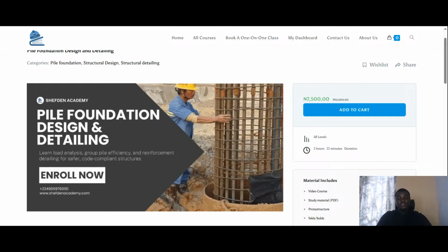what is important in this case is the minimum reinforcement required for the pile. So in this kind of problem, what is usually common in practice is, they will do 2 meters without placing reinforcements, just concrete, and then they will reinforce the remaining 12 meters. So that is what is usually common in practice as regards your question. So if you have a 20-meter depth, what they do is they do 8 meters without reinforcement, and then they reinforce the remaining 12 meters.